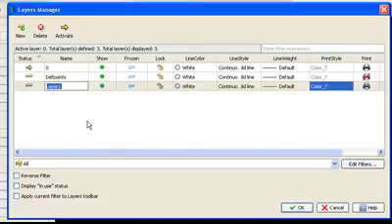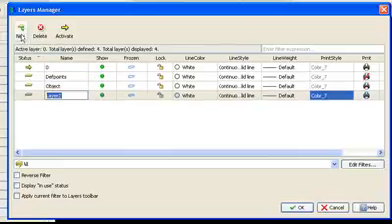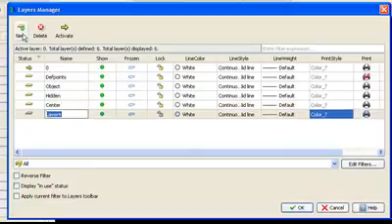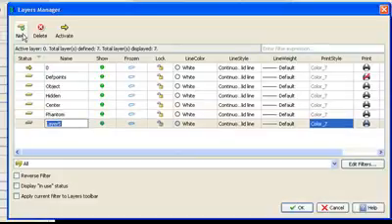The first layer I'm going to create, I'm going to call it object, and that's where we're going to put our object lines when we create a drawing. So I just need to create the name object. That's all I'm going to do for now, because I know I'm going to create a few more layers. So I'm just going to go new and create another new one. The next new one I'm going to create is going to be hidden, and this is going to be for hidden lines. I'm going to have one for my center lines. I'll create one for my phantom lines if I happen to need phantom lines, and my dimensions. Okay, so that's how I would start.